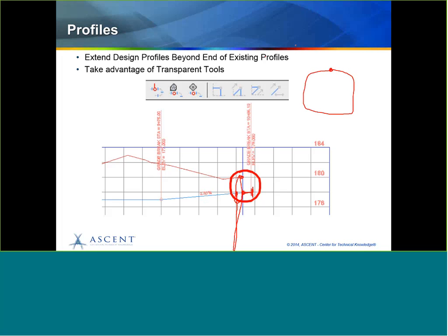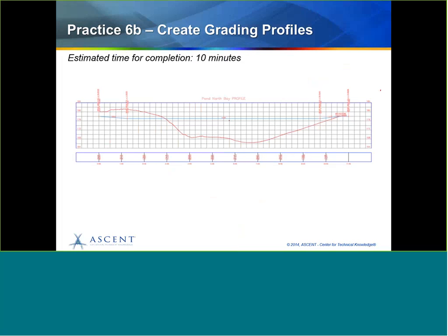Is it going to stay the same elevation, or is it going to change elevation? Well, to make sure that you don't end up with a wall right there where those two pieces enclose at the beginning and ending point of your alignment, what you'll do is make sure that your beginning station of your profile and your ending station of your profile are the same elevation, all right? So let me actually go show that to you.